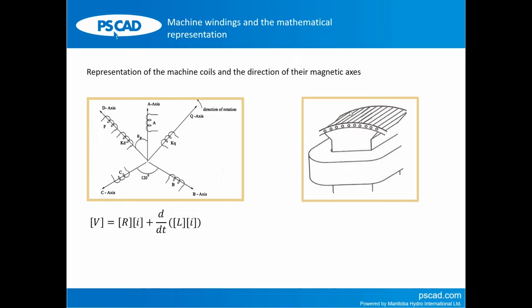And that would have a stabilizing effect on the transient. If the machine is speeding up, the induced currents would contribute to a torque that would try to slow down the machine, and vice versa. In addition, currents can also get induced in the iron of the rotor, eddy currents. So the impacts of these have to be considered to have a realistic machine model response.